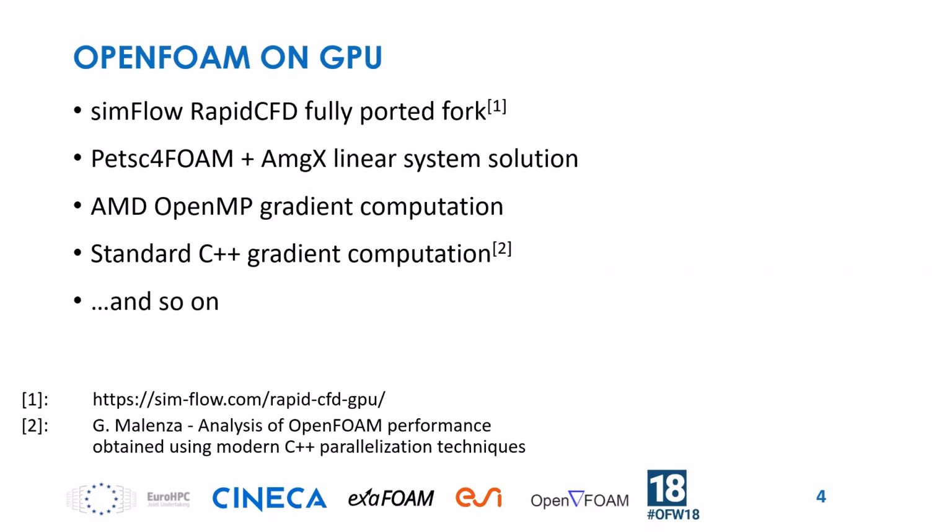And another approach, which we have seen a lot of examples in this workshop, is to take a piece of OpenFOAM, port that to GPU, and study the performance benefits of porting it to GPU. One popular target, for example, is the solution of the linear system, as we just saw. Another popular target is the gradient computation that makes for a very good proof of concept. If anybody saw Giulio Malenza's presentation yesterday.